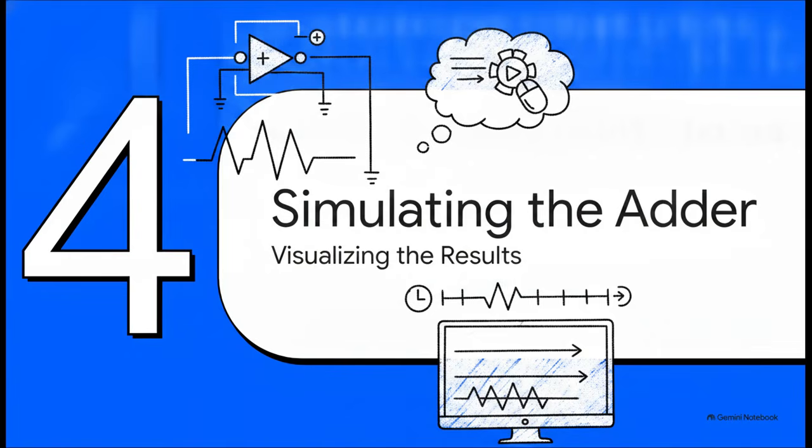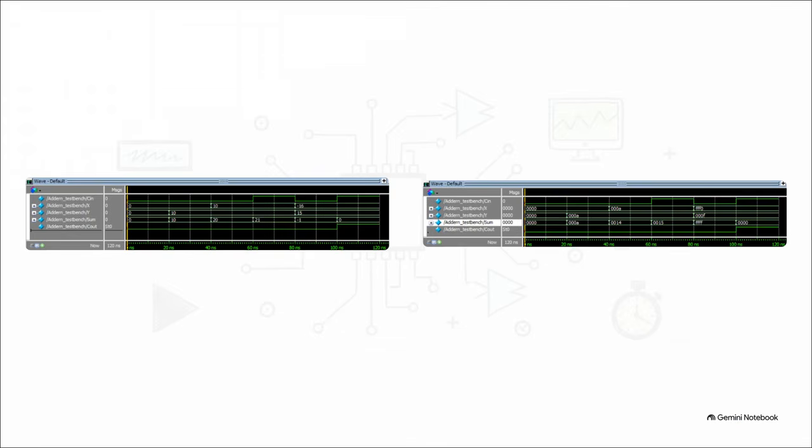Section 4. Simulating the adder. Visualizing the results. We've written the script, and now it's time for the payoff. By running the RTL simulation from the Quartus menu, we launch Questa. We pull our inputs and outputs into the wave window, set our zoom, hit run, and boom, we get visual proof of our code. And here is what that visual proof actually looks like.